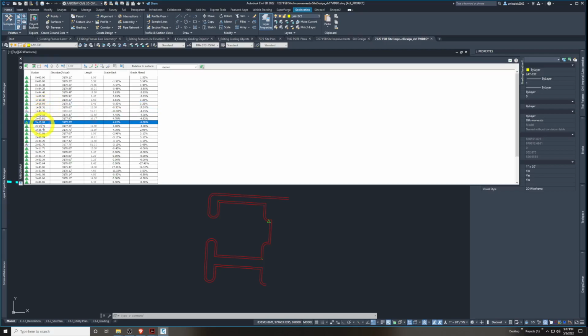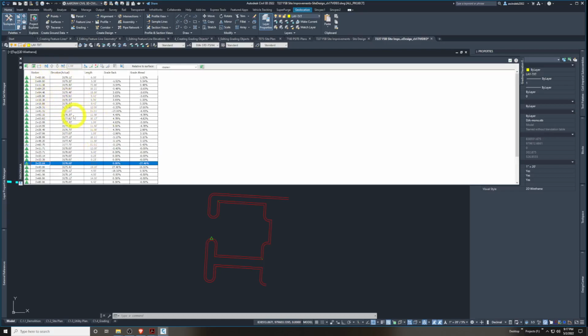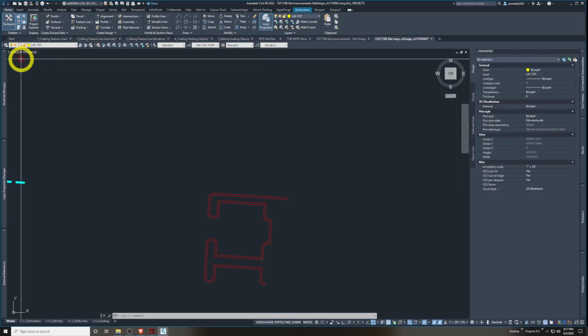And they can get kind of complex, unwieldy. I've had a lot of issues getting them to sometimes be error-free. When they get really big, huge, with hundreds of thousands of vertices, they can be very unwieldy. So you kind of want to break your design down into smaller chunks. But this is a little forethought into what is inside of these feature lines before we edit anything.